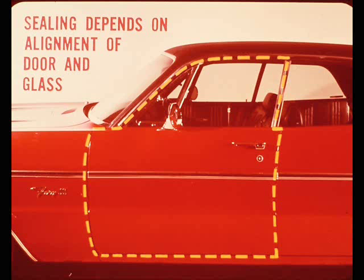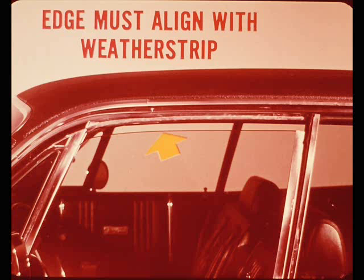On hardtop models, good weather strip sealing depends on proper alignment of both the door and the glass. The standards for door alignment and closing are the same as for sedan and two-door models. The top edge of the door glass must align with the roof rail weather strip to make a tight seal. You may have to realign the glass, but remember that any adjustment you make will also affect the fit of the front and rear ends.